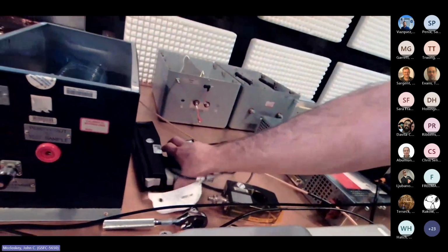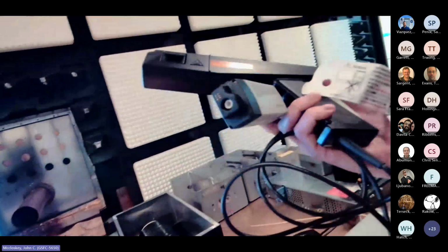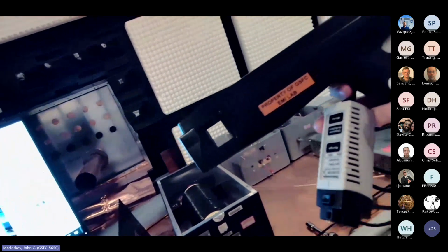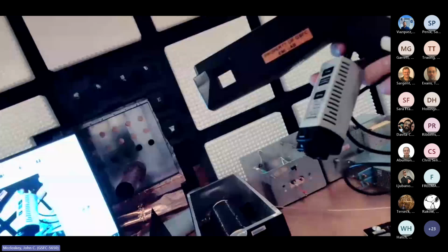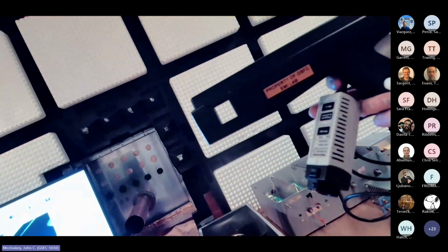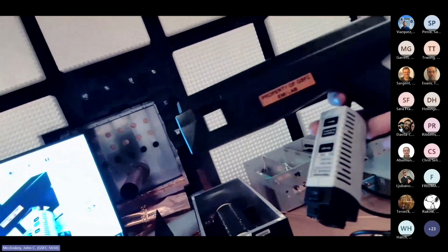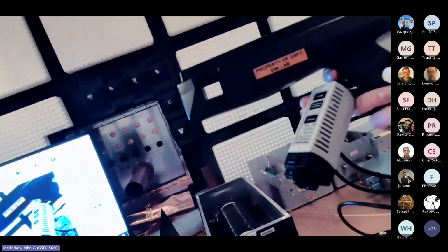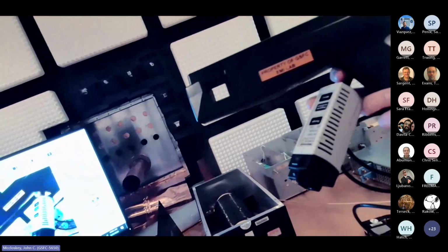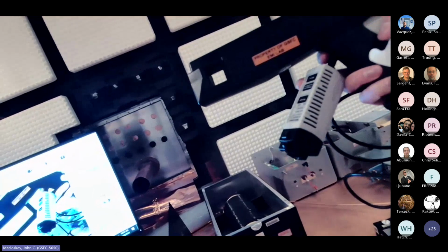But if you do have a probe meant to use with an oscilloscope like this one that has a larger aperture, this is sometimes called a gun type probe. We're gonna get it above that white background there. It's roughly a 1-inch aperture. So these are really good probes to use on full cable bundles. When you want to clamp around a full cable bundle to get a common mode measurement in the time domain, if you've got a probe like this, this is great.